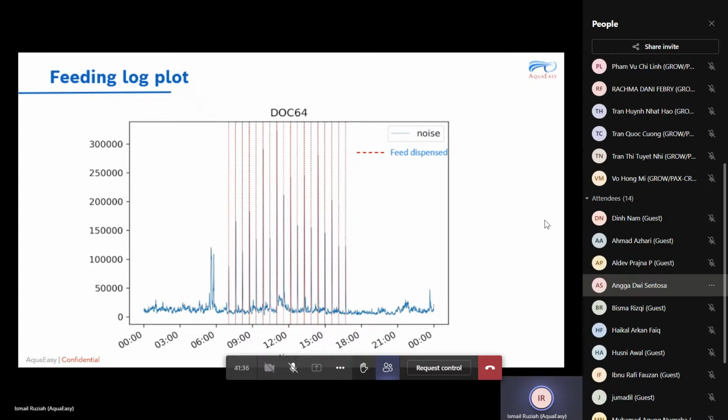If we don't use a sensor, the shrimps will also react and start getting stressed, and they'll maintain that high stress level. The problem is that when we don't have a sensor, the system will reduce feed, but we won't know what the DO levels are. So there's no way for us to track this except somebody going there to measure it. So far, this is the only parameter that we integrated. The other parameters, we have thought about, but we haven't yet included them.